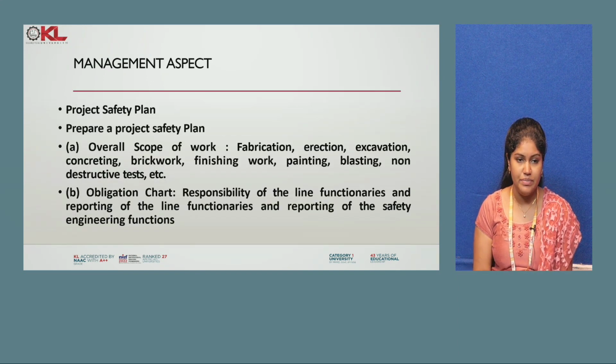A project safety plan should be prepared, and overall the scope of the work has to be mentioned in it: fabrication, erection, excavation, concreting. That means from the starting till the end, there should be proper planning. Obligation chart, responsibility of the line functionaries and reporting of the line functionaries. Based on the safety engineering function, the responsibility of each and every person has to be mentioned in the plan.